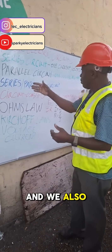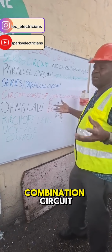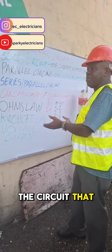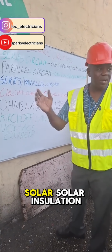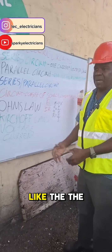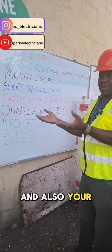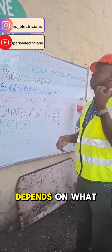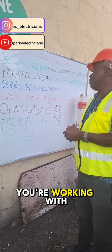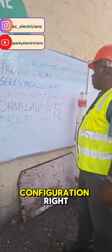And we also have a series-parallel circuit. In the United States they refer to it as a combination circuit, which has some part of the circuit connected in series and some part connected in parallel. And we have solar installation, where they normally connect the modules in series and parallel, and also your batteries, depending on what type of power you're working with. So you have the series-parallel configuration.